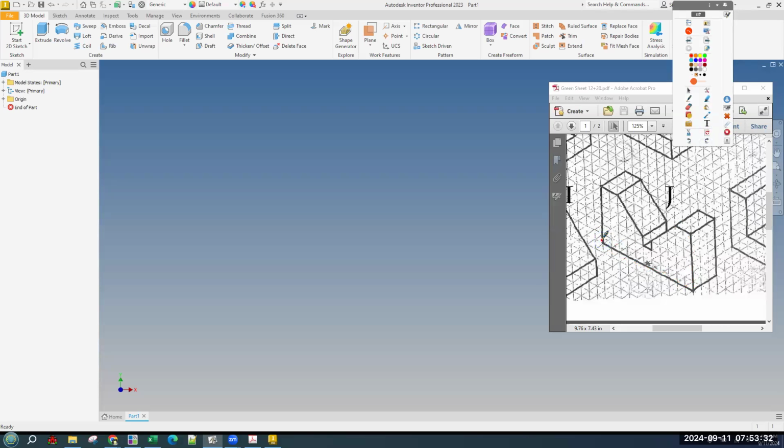Because with the way we make the rectangle, or any of the shapes where we make it whatever size and then dimension it, if you do that with lines, sometimes they'll flip the wrong way. It's just guessing the way you want, but it guesses wrong sometimes. The other thing that's different is now you will be punished, figuratively, for clicking and dragging rather than clicking once to start and clicking again to set.